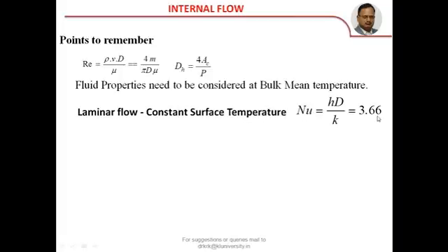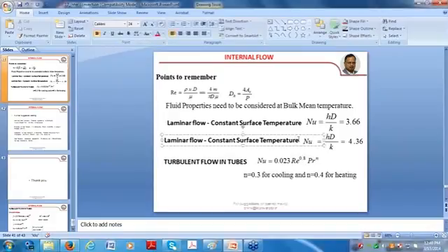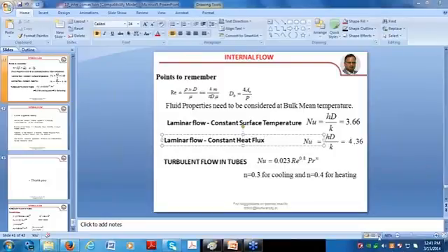Finally, we have to calculate the outlet temperature, and if the assumed value and the calculated one are the same, it is okay. Otherwise, we have to go for iteration by assuming another value, which is the one we have obtained in the first case.